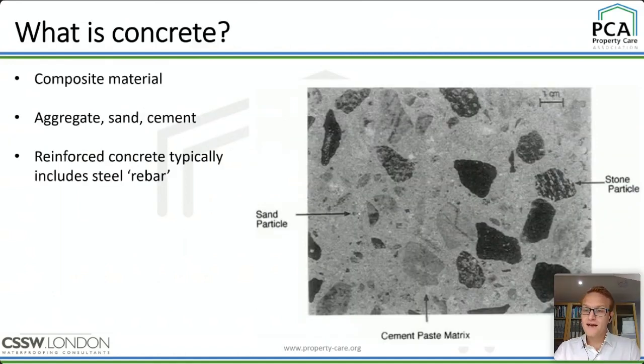What is concrete? Well, in some ways, very simple. You've got some stone and some sand and some cement. We would typically call stone an aggregate, but actually, the more you drill down into the detail, the more complicated it becomes. So really, this section should include some rebar, because reinforced concrete would include reinforcing, which is typically rebar. That's steel rods. But in addition to your stone, your sand, your steel, and your cement, you have voids and you have water.